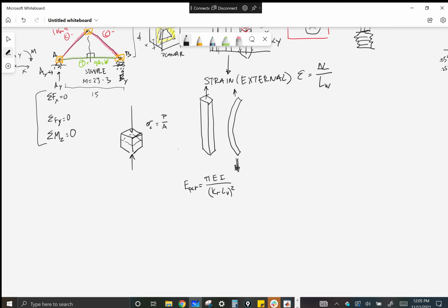Resistance to buckling about an axis, moment of inertia. Is it a material property or is it? Yeah. Geometry, right. Now, it's geometry in the context of material, so we can't use it without the E. But right, it's geometry based. But now we're not talking about truss geometry, we're talking about cross-sectional geometry.